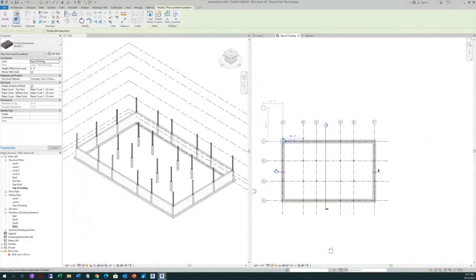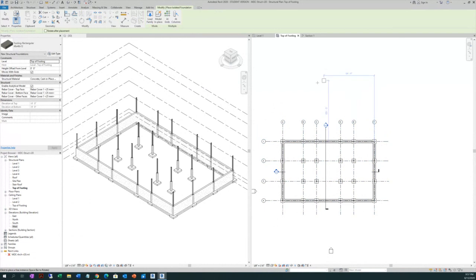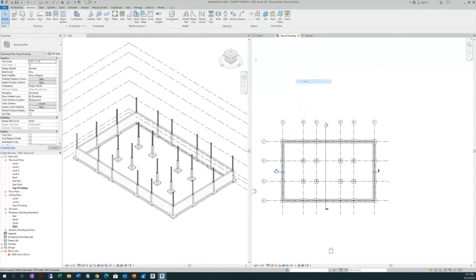Or remember, you have this on your option bar, the add grids. Take advantage of that. Add grids. Then do a crossing selection from the upper right side to the opposite, left down. And in one shot you have it. Right? Then you go and close the mode. Finish mode. Finish. It may still be active. You need to cancel twice or escape or modify. Okay? You got it? Yes. Okay, now save it. Save it, please.